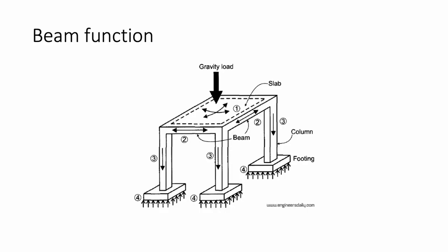Basically the slab will take the vertical load and do kind of 2D load distribution, and then the beams will receive a vertical line load, and then transfer the load horizontally to the columns, which will transfer it down there. So basically, the main stress would be horizontal stress.